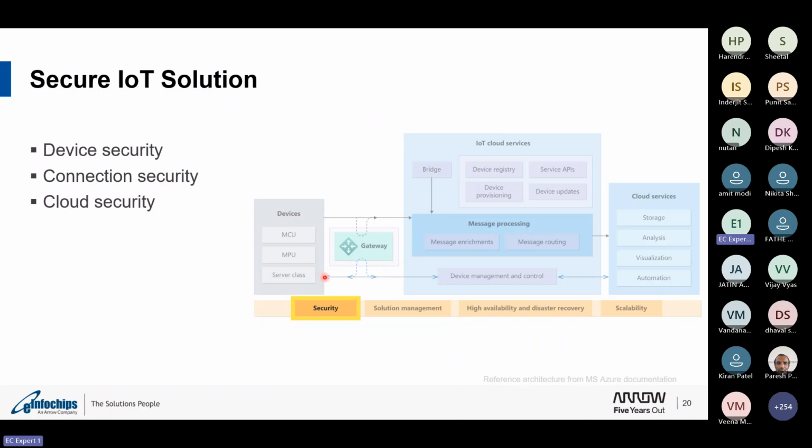We can also use transport layer security. So your devices can communicate through HTTPS, where if you are using HTTP as a communication protocol, the device can use the secure layer to communicate securely with the cloud. Similarly, you can consider using MQTTS, or secure MQTT, which comes with the certificate or the security toolchain that communicates back to the cloud and the device.